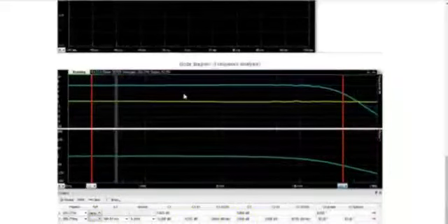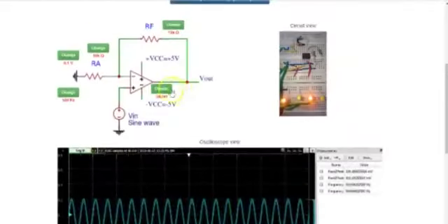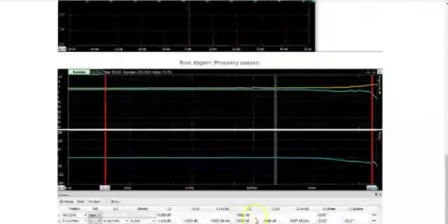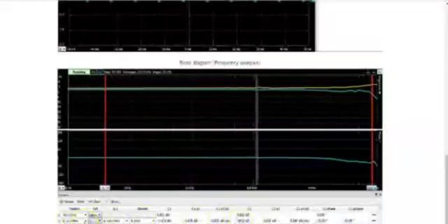The above process is carried out for another op-amp OP37 with better performance parameters. In the first case, with Ra equal to 1 kΩ and Rf 10 kΩ, the voltage gain is 20.805 dB and 3 dB bandwidth is 8.132 MHz. This shows that the op-amp OP37 with larger open-loop gain has better bandwidth compared to that of UA741. Like this, the analysis can be done for other combinations of resistors, signal amplitude and frequency.